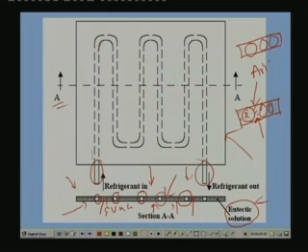That means when you have a lot of solution in the evaporator, a lot of external fluid in the evaporator, the external fluid, since it is a liquid, has large specific heat, and it also has large mass because of its high density. So you have large m cp liquid which is cooled to almost the same temperature or a few degrees higher than the evaporator temperature. That means you have an evaporator which has a large thermal capacity and which is cooled to a low temperature. Now let us say that there is a power cut.